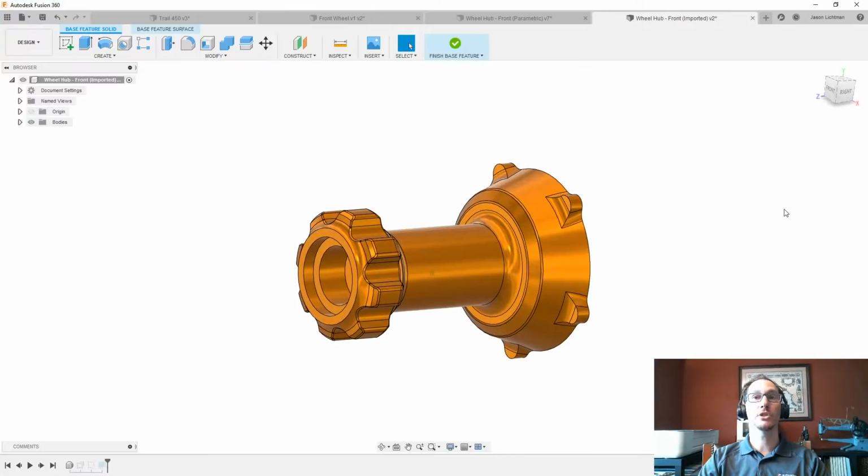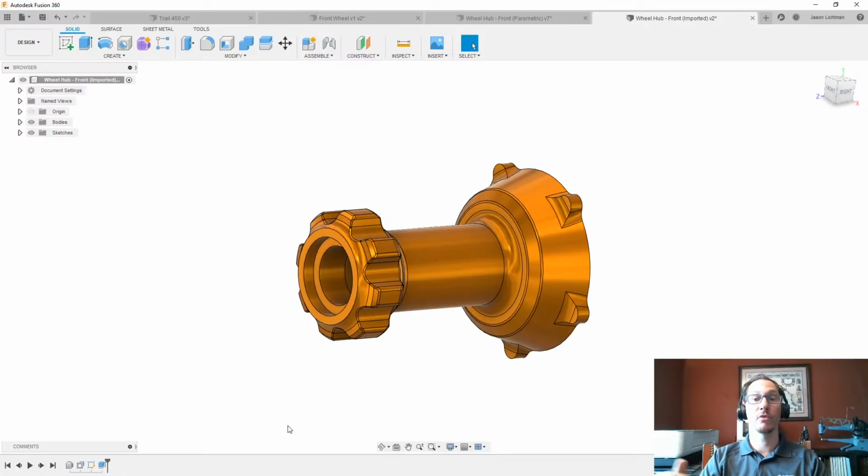And now it changed the geometry. And when I hit finish, I wind up with exactly this finished geometry before I created my offset, before I created my sketch for the keyway or the extrude for the keyway. But there is no feature to actually edit to be able to change that 1 inch to half an inch or 3 inches or whatever it is. Now, that might seem like a negative, but actually it's not. There are a lot of positive reasons why you might want to edit an object and not keep the history.